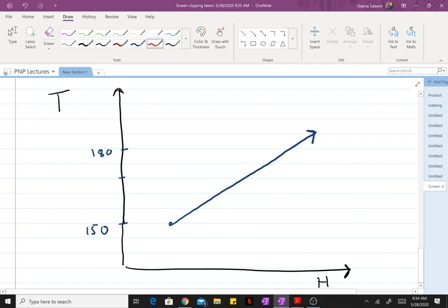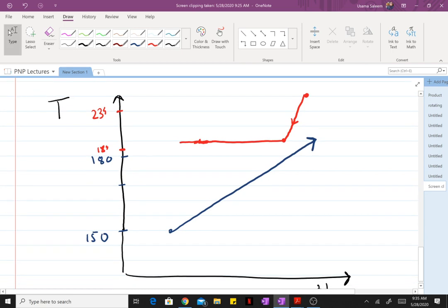And I have my heating utility. Now the heating utility enters at 234 Celsius. Okay, it becomes saturated at 184 degrees Celsius. And when the steam is condensing, the temperature is going to remain constant. And finally we set the exit temperature to be 174 degrees Celsius, so somewhere around here.